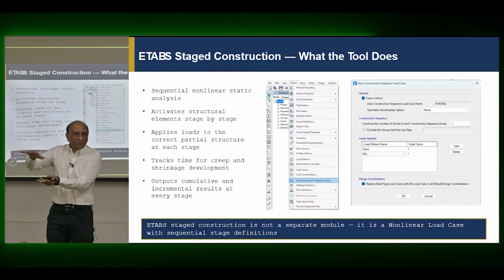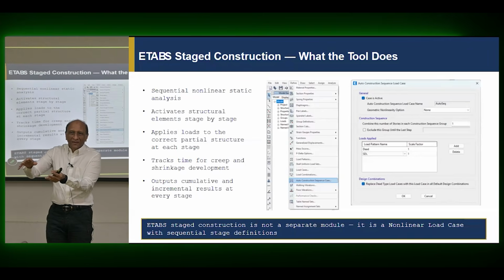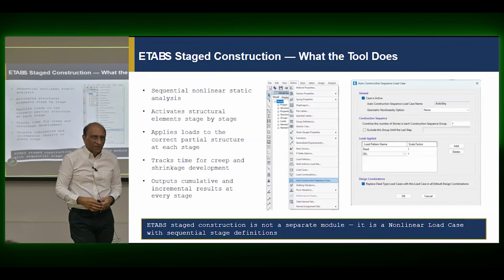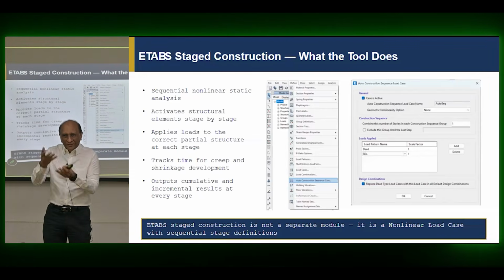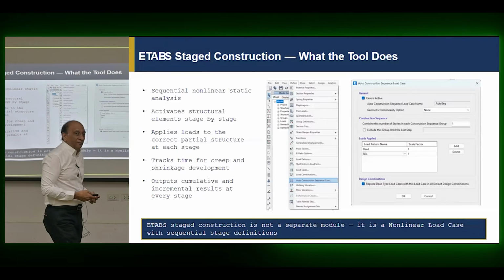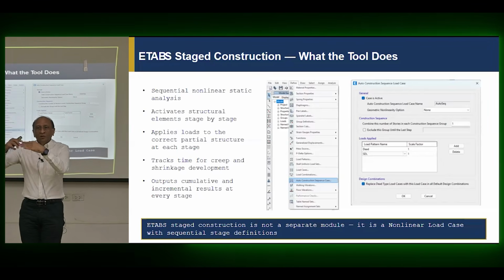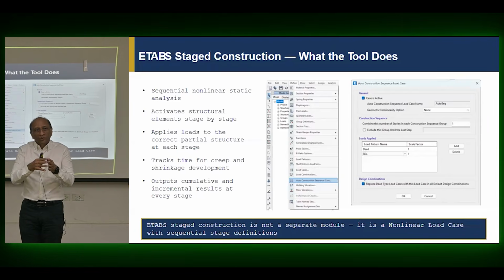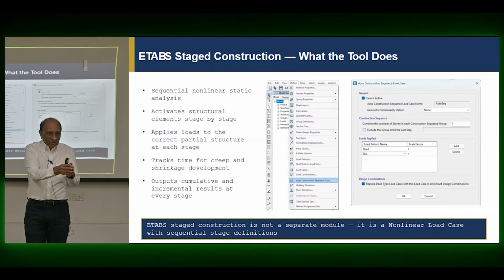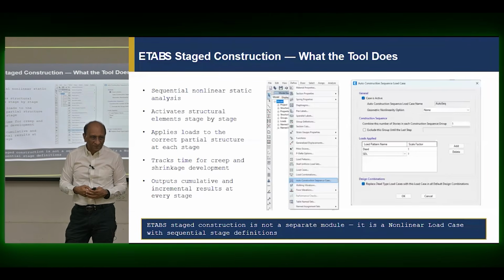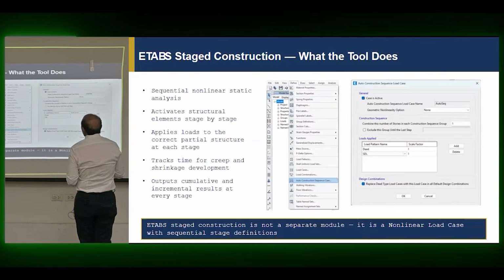So it will create a group of 5 floors, stage 1, add group, add load, go to next, add. That's a very simple way of doing things, right? You don't have to consider every floor as one stage because it's unnecessary. 3, 4 floors together is fine for preliminary estimation. So that's just about the process. It's not complicated. Then comes the long-term analysis, which is a separate one, that you do with age assigned to the groups, right? This one, construction starts from here to here, creep, this one, this. So those 2 things are there. That's the short summary. So that's how you add it.